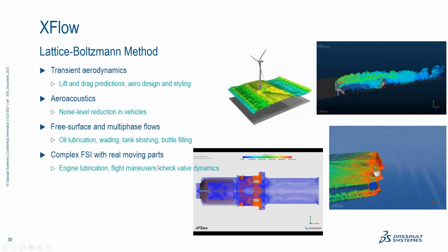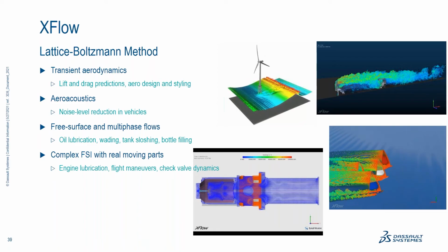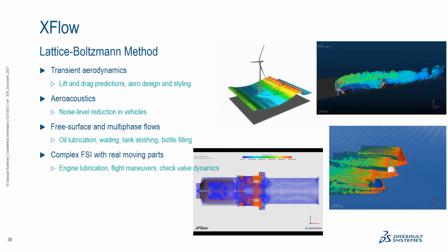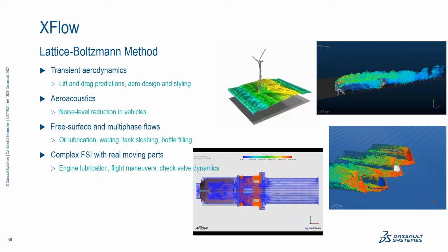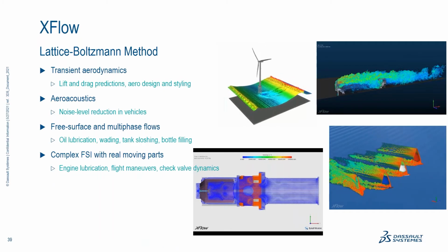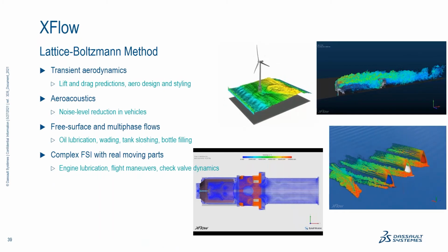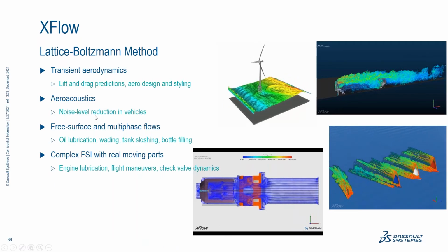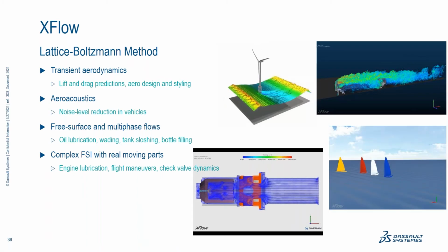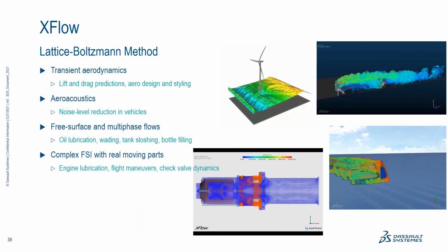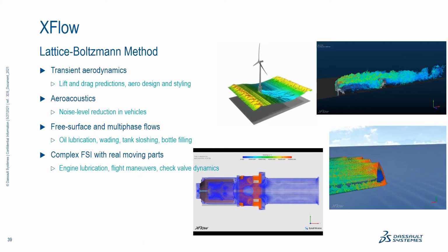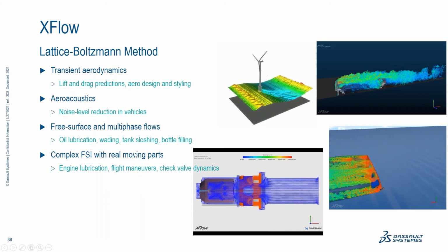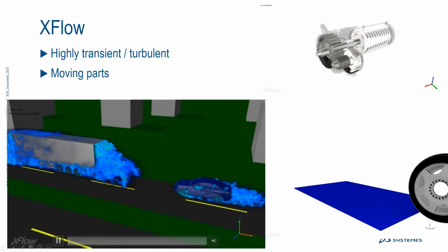I mentioned in flow simulation, you can do a one-way fluid structure interaction, in the sense that you run the flow analysis and then you export, or the program does it. You tell the program to push the results in terms of pressure and force distributions to the stress analysis package, and you run a stress analysis there. That is a one-directional interaction from flow into structure. Whereas, if you want to do a full-blown FSI, or if you have, for example, moving parts, then you have to look at the problem differently.